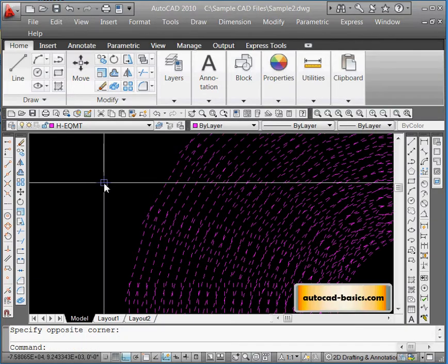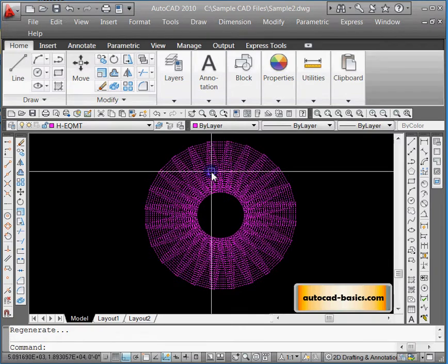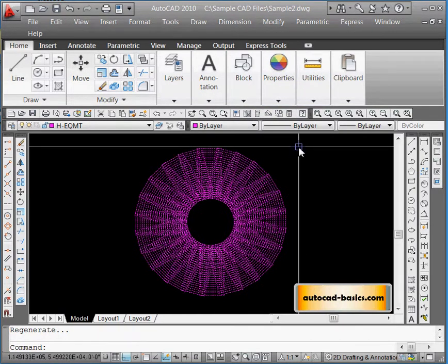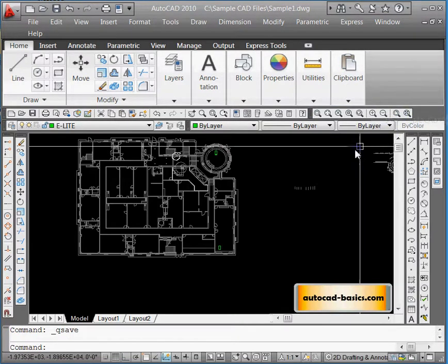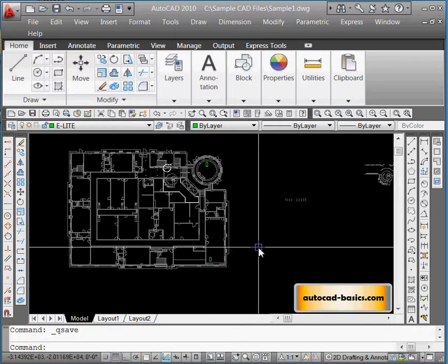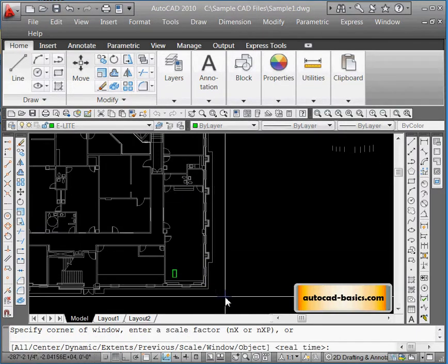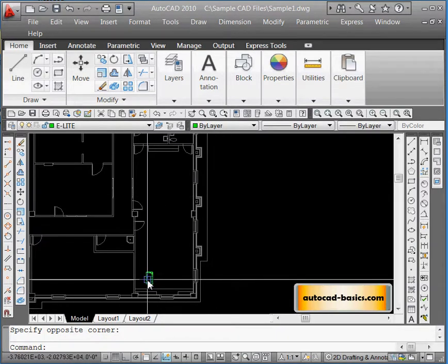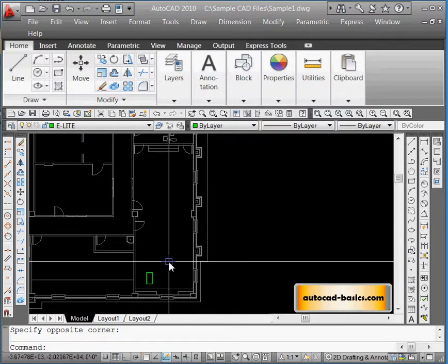And moving on, let's look at a real-world example of how this will be used in an engineering drawing. Here we have a plan that could either be an electrical plan or an architectural reflected ceiling plan. And let's start here with this room. I know I want to do 2x4 lights in here, and I want to spread them around approximately 10 foot on center. So first we're going to go into array command, and we want to do a rectangular array.